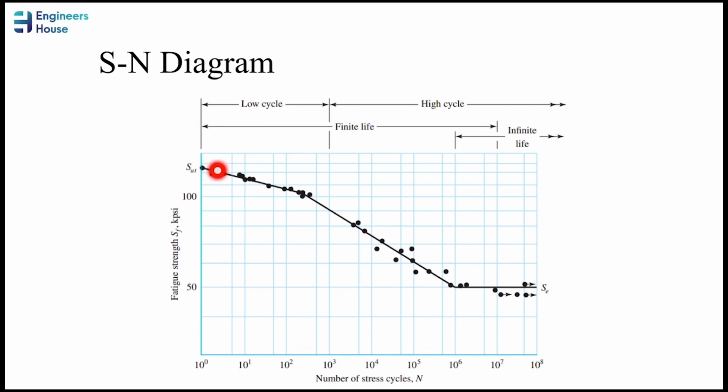First of all, this dashed line tells us a lot about fatigue failure. If your design component is under this line, it means that you are in the safe area. But passing this line will cause you some problems. Your component will be totally unsafe, and within any cycle it will fail. Sometimes not even statically, but in a fatigue way.